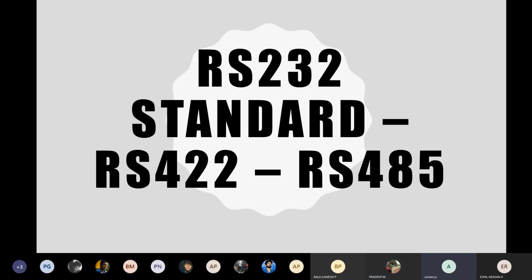So this register is used for the communication purpose. Okay. So SCON is nothing but, first we will go through the PCON. PCON first is a power control device. In this register, 2 bits will be there. It will tell whether the microcontroller is in idle mode or power down mode. Okay.